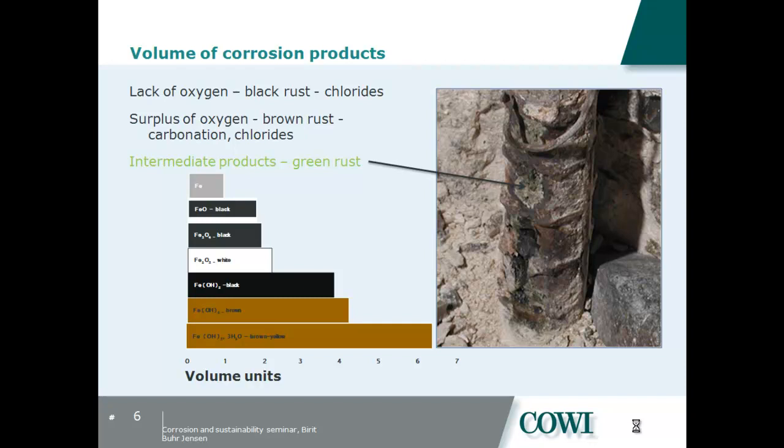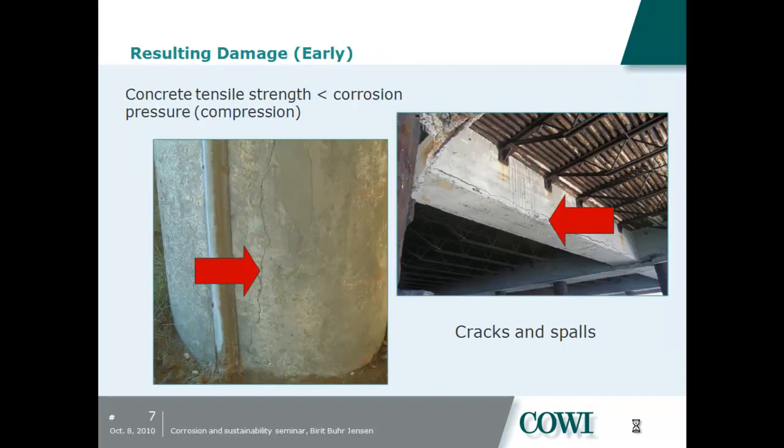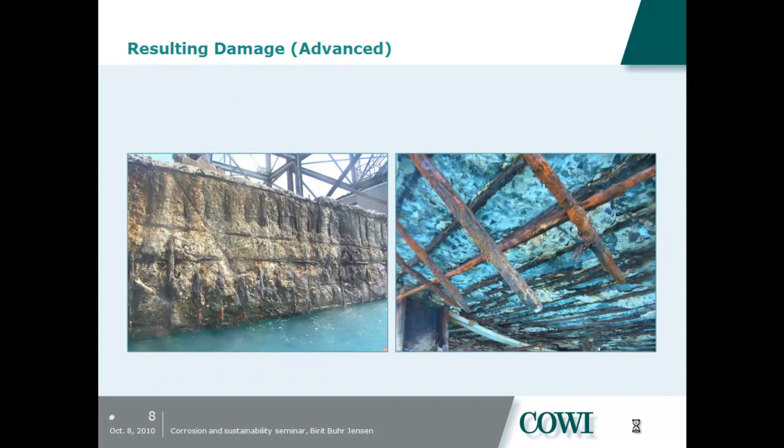This reinforcement bar, making an excavation looking at the reinforcement, you can then see it actually change in color as oxygen accesses it. So you start off seeing a black steel, and it will then turn into green and white, and if you wait long enough, brown. We know when we have oxygen enough, it will cause concrete to crack. And sometimes we can even see, as on the as-built drawings, the reinforcement that is.